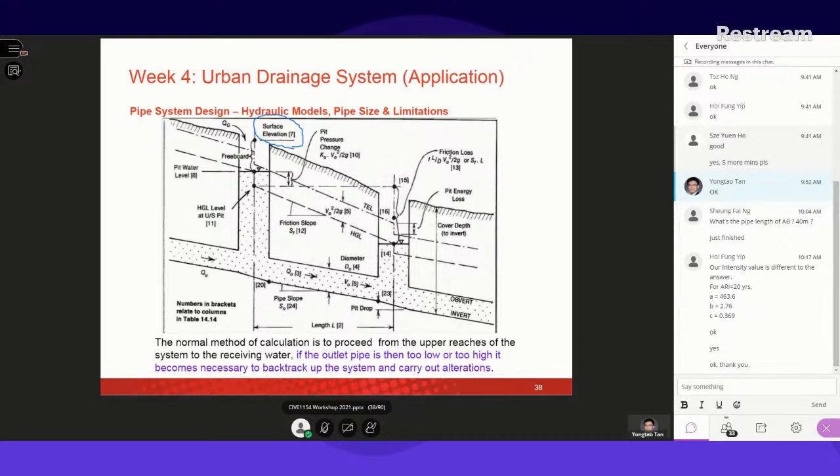In pipe flow, the energy changes, and there are also energy losses. For example, going from a higher elevation to a lower elevation, part of the potential energy changes to kinetic energy, if there is no change of pressure. Of course there are energy losses from the upstream to the downstream pipes.